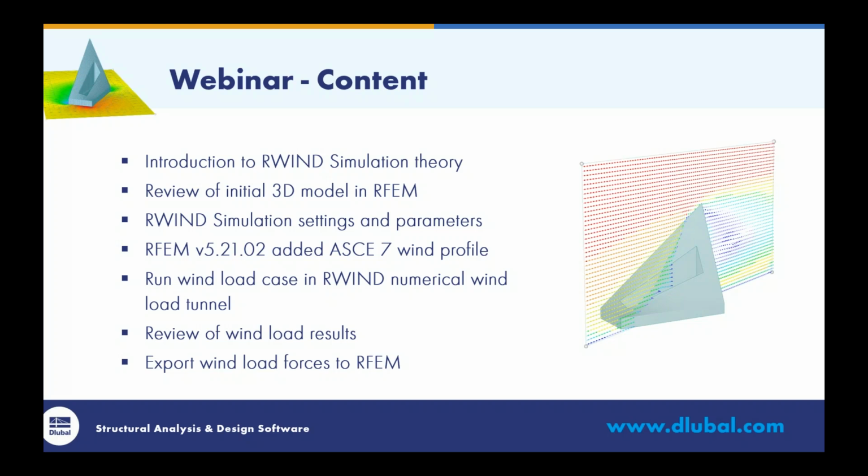Then we can run a wind load case within RWIND, which is within a numerical wind tunnel. From here, we'll review the wind load results, and then finally we can export these wind load forces back to RFEM to continue the analysis and design of our structure per usual.